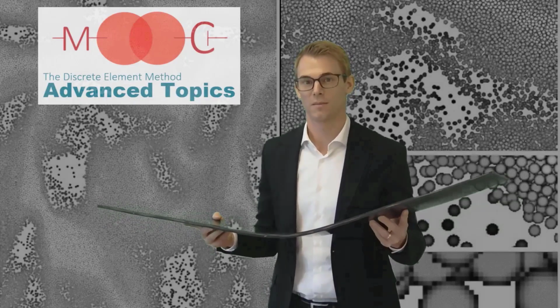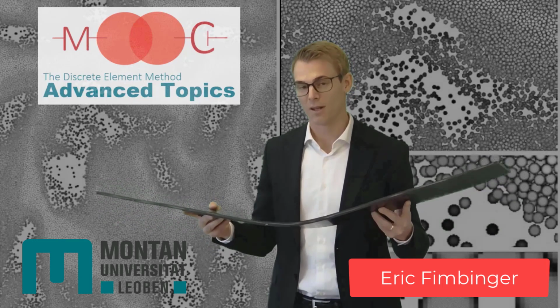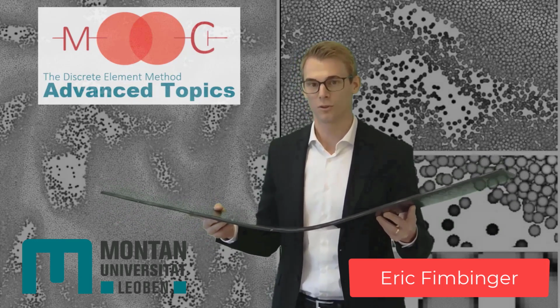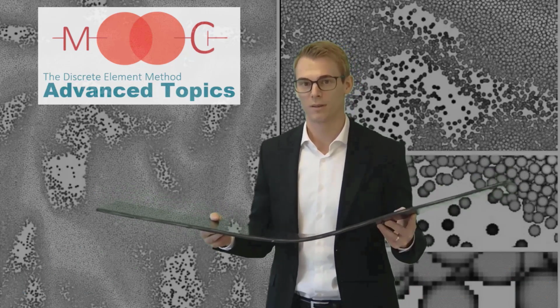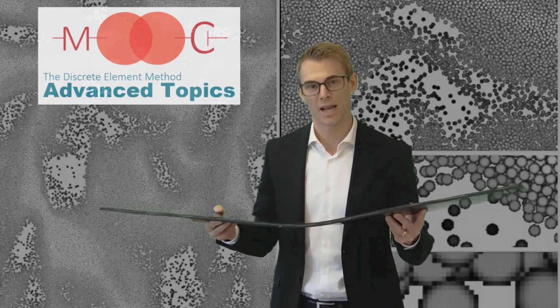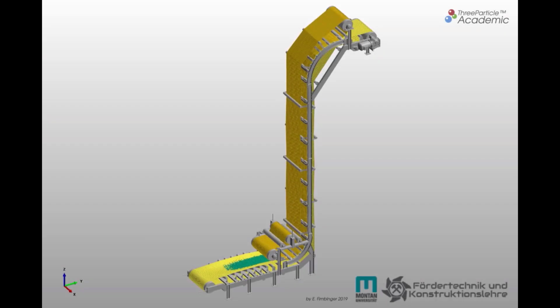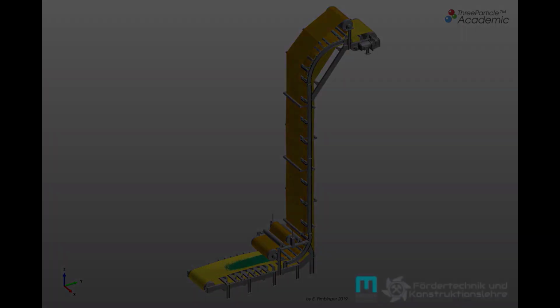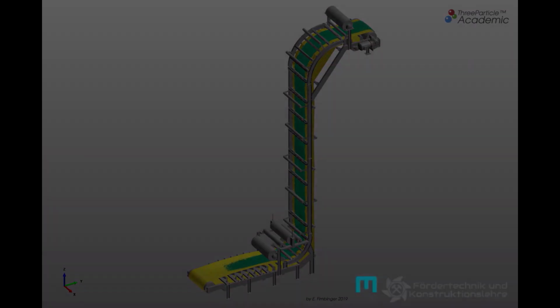So when set up as a bonded particle model, the belt is able to react dynamically and locally to loads from the bulk material on the belt, as well as to components keeping the belt in place, such as idlers and pulleys. An example of a belt conveyor system where this can be visualized is a sandwich conveyor, where the deformability of the belt is of significant importance. This system transports the material with it clamped between two belts.